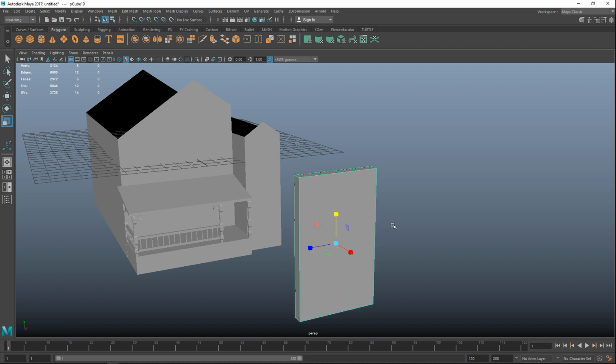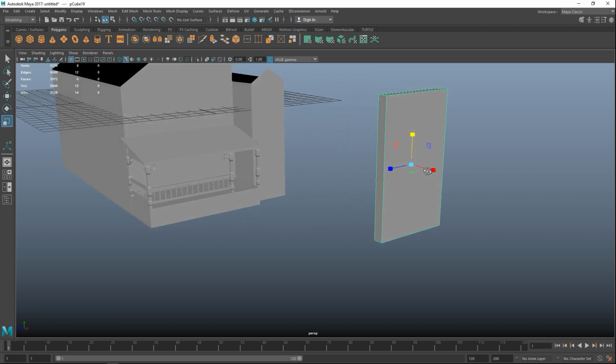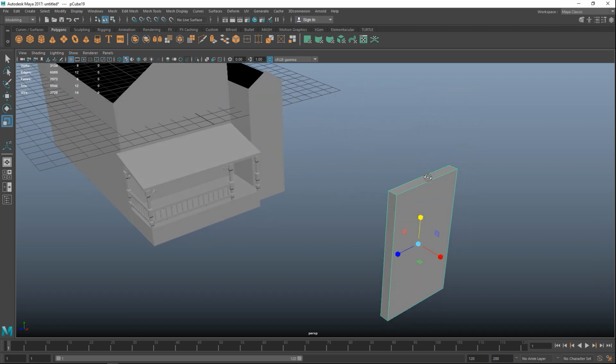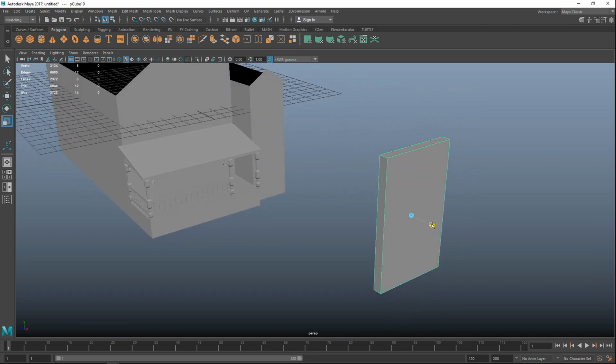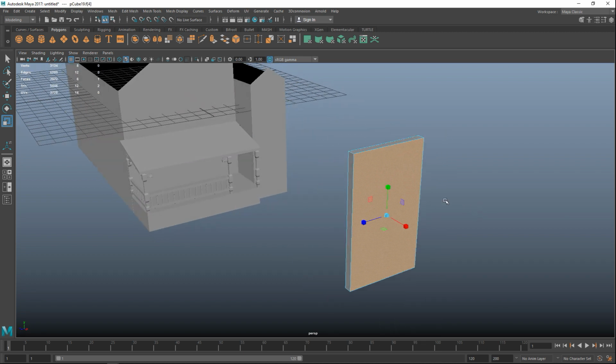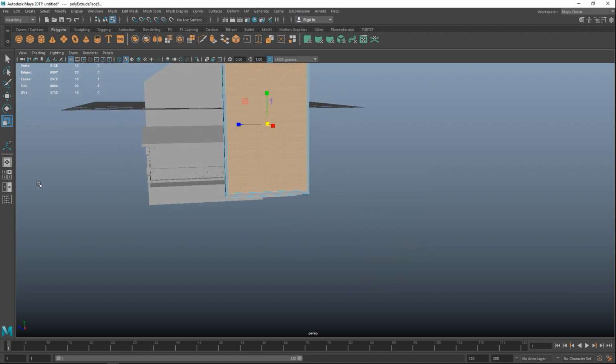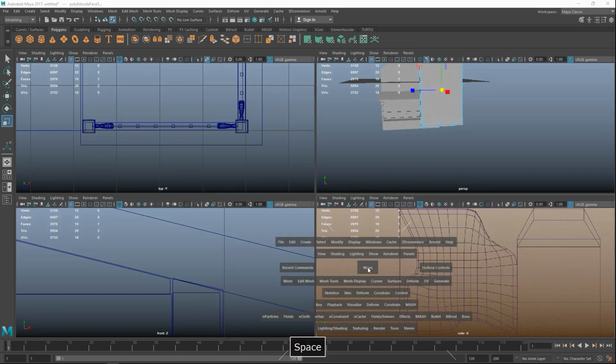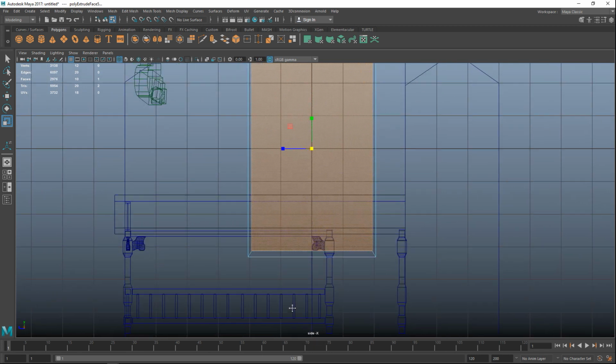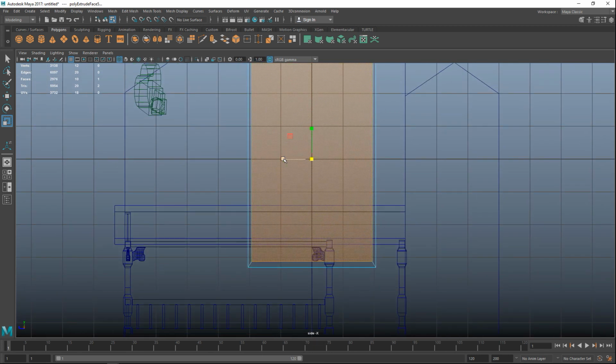and raise it up. Now, what I want is slider windows. So I'm gonna push it in some more. I'm gonna select this, right click face, and I'm gonna hit Control E to extrude, R to scale in. And now I need to do that manually, which is kind of a pain in the you know what, because I don't have that little menu anymore for whatever reason, like so.